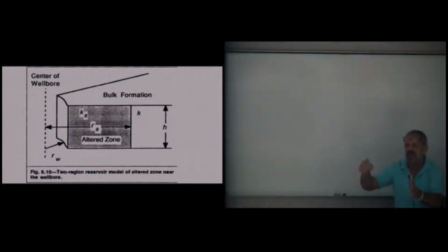It's hard to do this beforehand, so usually we rush to judgment. I've looked at a lot of these, this is the middle time region. And then when we get a permeability calculated, we can determine if it's that permeable, then yes, our wellbore storage period should have ended by now, and we indeed did pick the right middle time region.